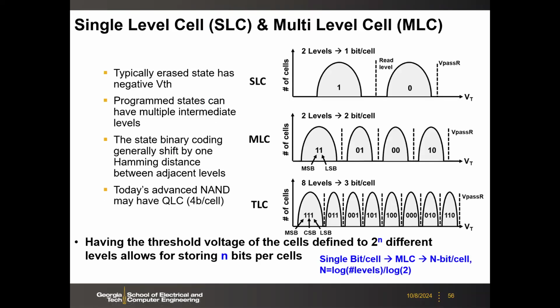So here, to increase the density of the NAND flash, we can use this multi-level cell operation. So what does that mean? That means in one flash transistor, we are going to store more than 1 bit of data. It used to be that in a flash transistor, you either have electrons or you do not have electrons, and then you have the data 1 and 0.